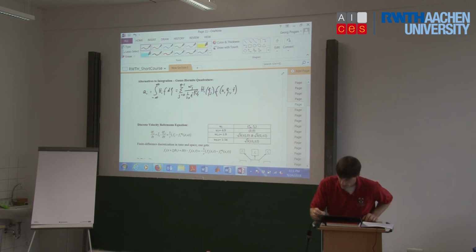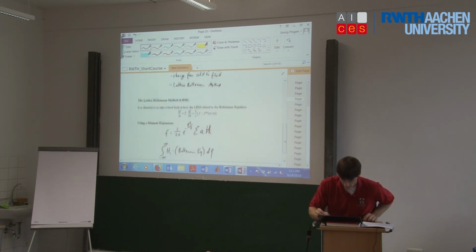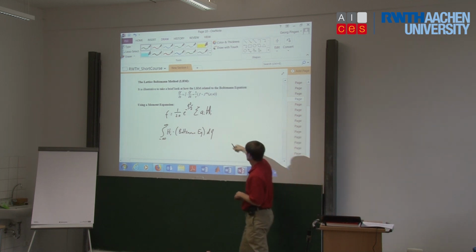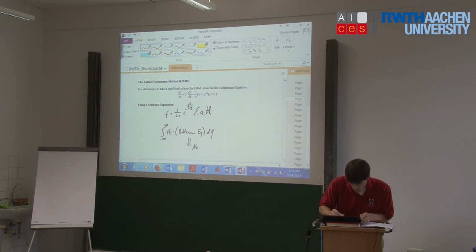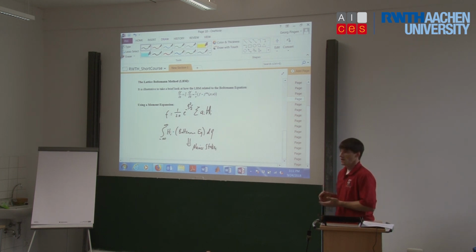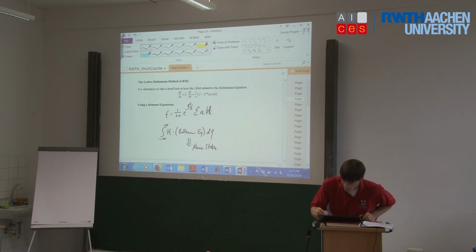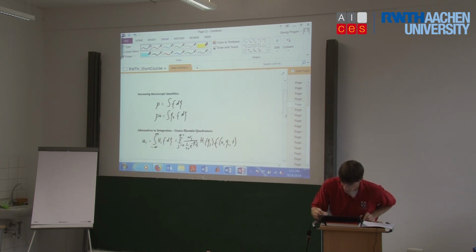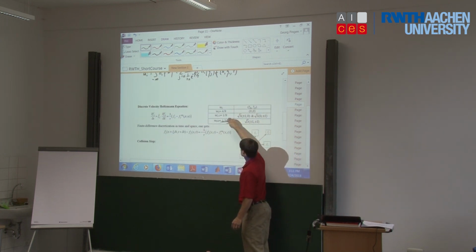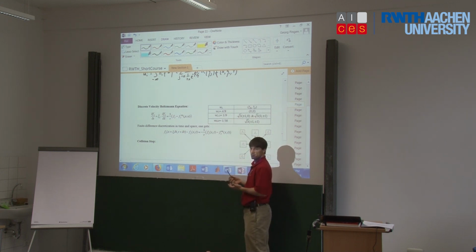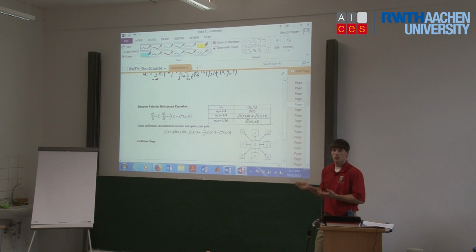So these second order moments right here then get us Navier-Stokes. If we, instead of taking the moments and using continuous functions, choose our coordinates correctly in velocities, we can just evaluate our function at 9 points of accuracy and approximately recover the Navier-Stokes equation.